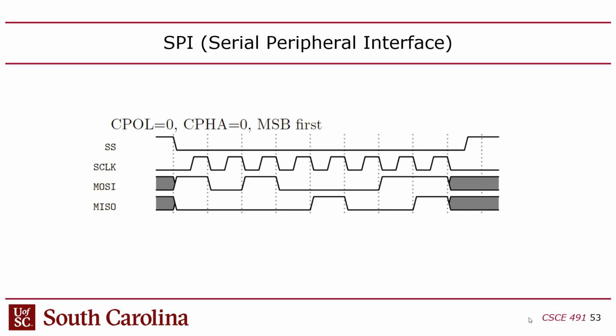But the concern about SPI is that we want to avoid the receiver becoming metastable, meaning that the whole problem that SPI is trying to solve is that you don't want the driver changing the signal at the same time that the receiver is sampling the signal, because that violates the dynamic discipline and it will cause the receiver's sampling flip-flop to go into metastability and it will cause an error, right?